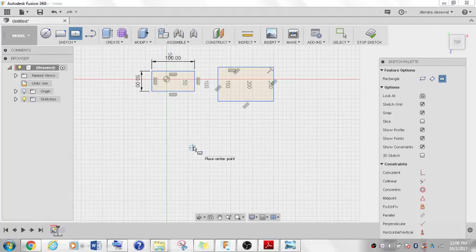We only have to specify the center point of the rectangle, and then give the dimensions, 100. For going into the second tab, we click the Tab key on the keyboard. It will take you to the next field, and then we give the dimension of 160 mm.